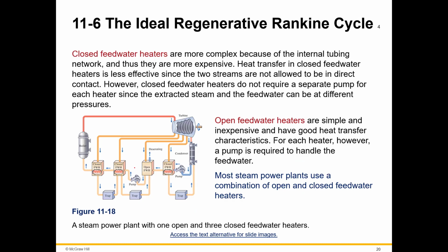Closed feed water heaters are more complex, of course, because of the internal tubing network, and thus they are more expensive. Heat transfer in closed feed water heaters is less effective since the 2 streams are not allowed to be in direct contact because you lose some of that in that barrier, which is this tubing. However, closed feed water heaters do not require a separate pump for each heater, since the extracted steam and the feed water can be at different pressures. So you don't need each one to address the pressure situations of the 2 mixers.